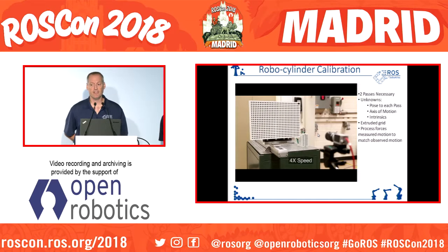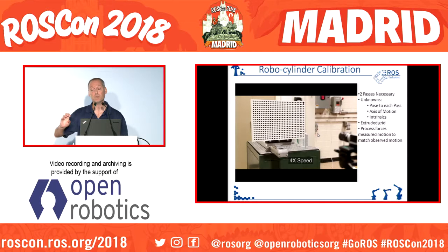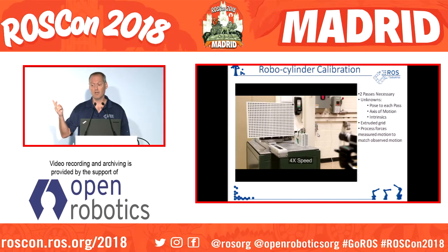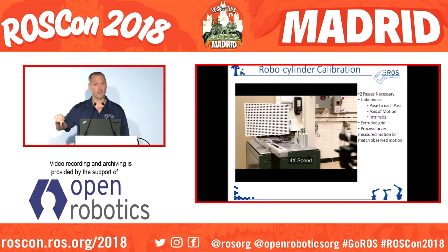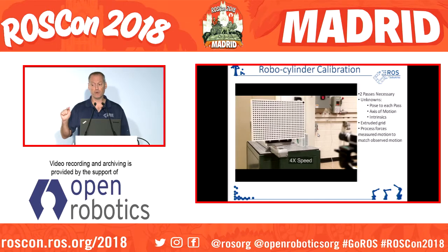Here's the example of the intrinsic calibration, and in this case, we're taking all planar pictures. Somebody might complain about that. If you are interested, I can describe why this is an okay thing to do, but we have to move the camera once. So we're only computing two different poses, the pose between the camera and the starting point in each case, and then the axis along which that rail moves in the target's frame. If we do those two, we get very good intrinsic calibration consistency.